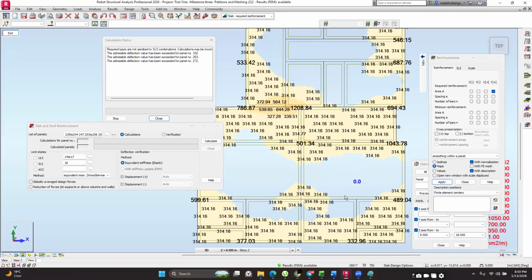So what is going to be happening is that this slab is experiencing some deflection here at the center, and then near the support, it has hogging moments. And this slab as well, it's the same. It has deflection near the centers, and then near the support, it has some hogging moments. So this one here, because of its small dimension in this direction, is going to be majorly experiencing some uplift.